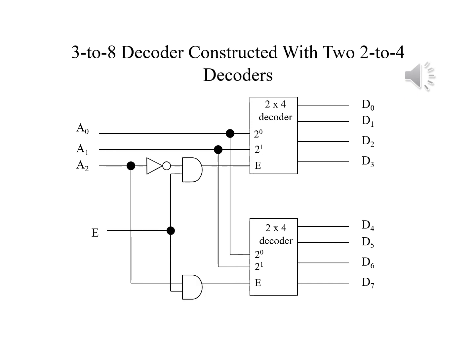It seems that in constructing our 3 to 8 decoder in this fashion, we've sacrificed the ability to have an enable. That's not necessarily the case. What we can do is split the enable and have it ANDed with A2 prime for the lower and A2 for the upper. In this regard, we still have a 3 to 8 decoder built out of 2 to 4 decoders, and in both cases, the enables are still available to us.